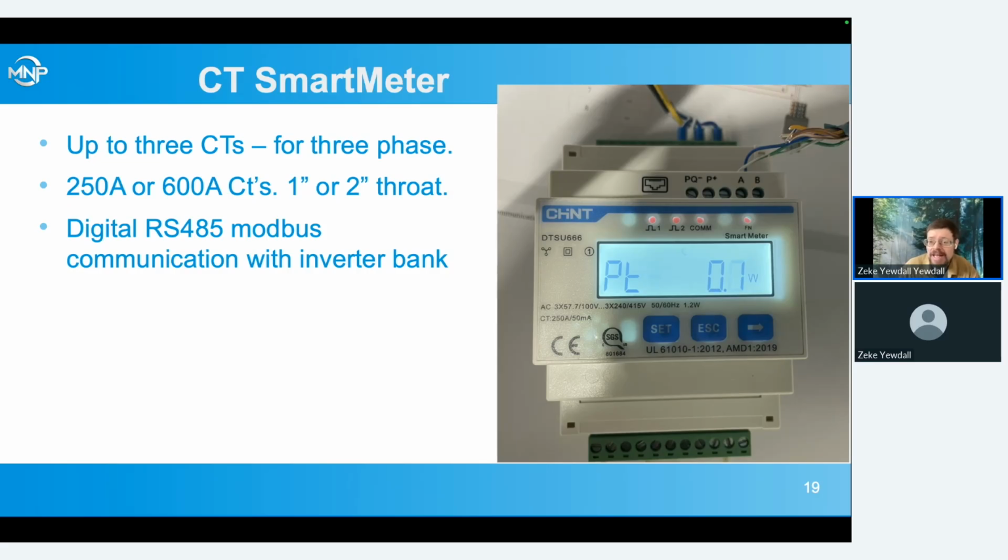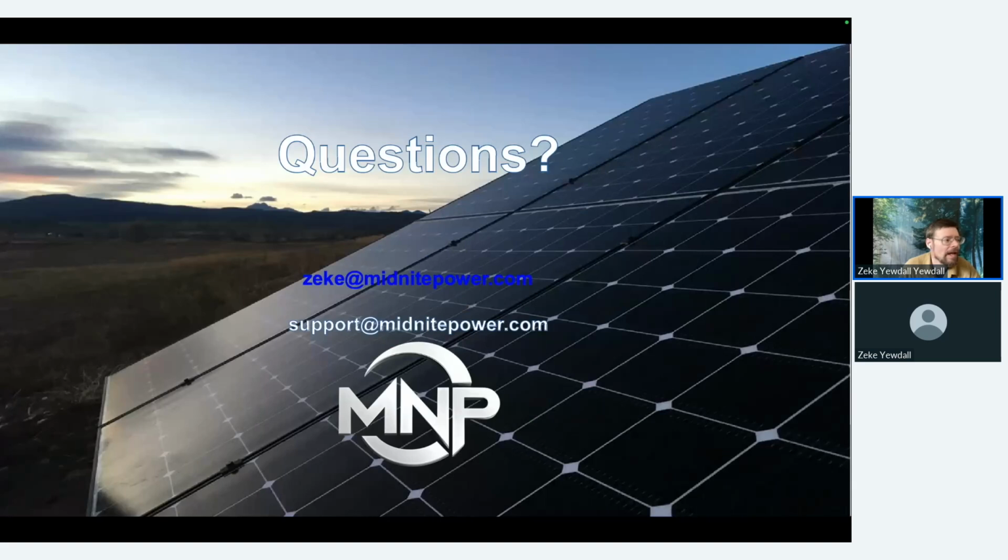So you may be having to get a separate little NEMA 4X 8x8 box to mount this in out by the service if you're connecting it. So that's a thing to consider when you're using the smart meter, that it's often going to require this extra little box for somewhere to put it. And that is what I've got on CTs for now.